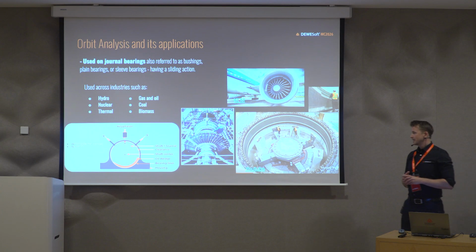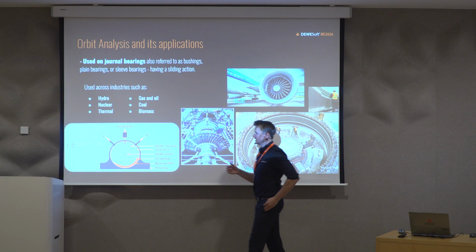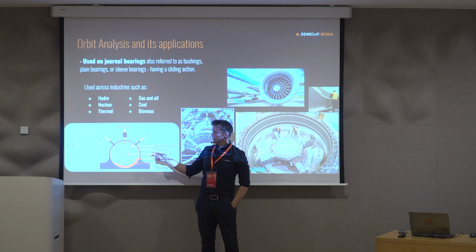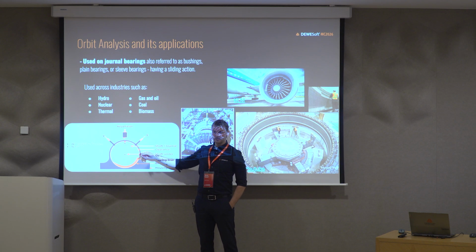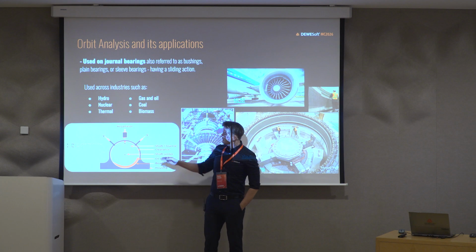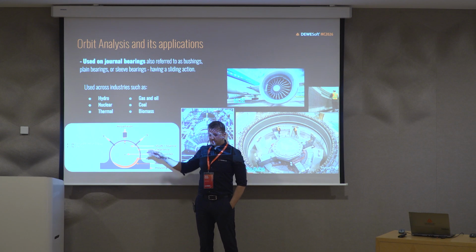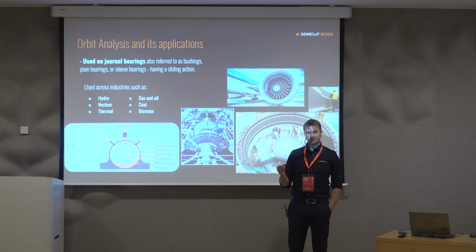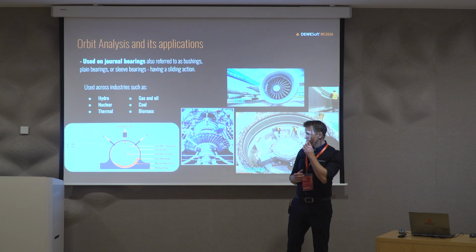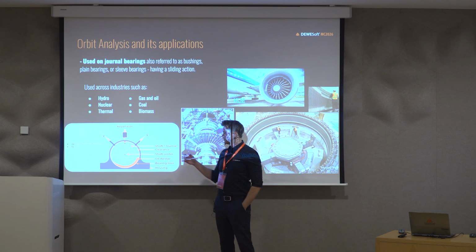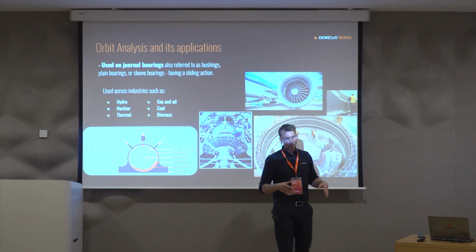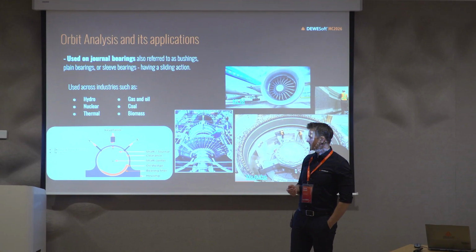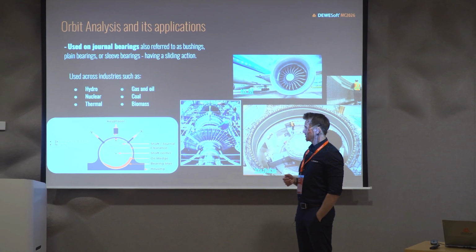And all that is done by having this kind of setup where you have not accelerometer sensors, but distance sensors, proximity sensors, which are constantly measuring the DC offset, the static displacement of the shaft center, and also if there are any movement inside. And also depending on the thickness of the fluid and how much there is of that fluid, that can also give some phenomena you want to measure.